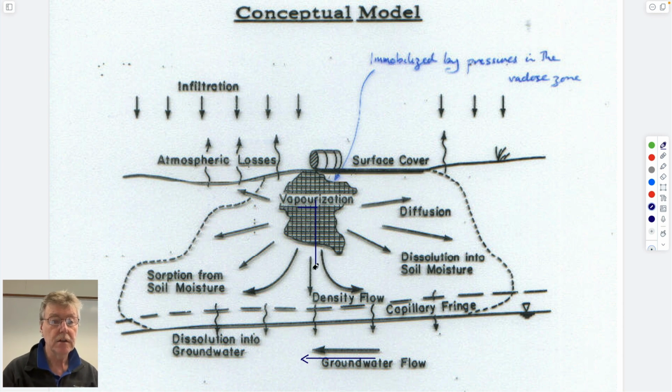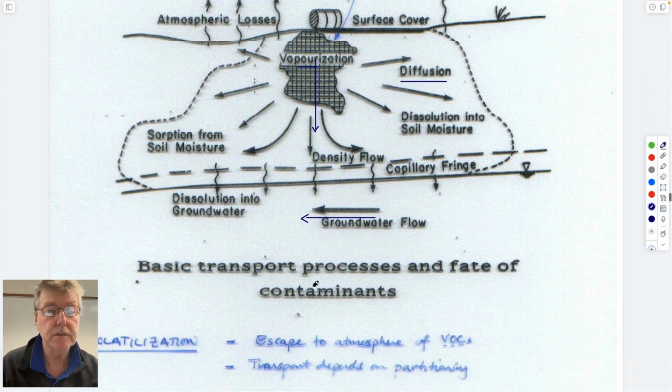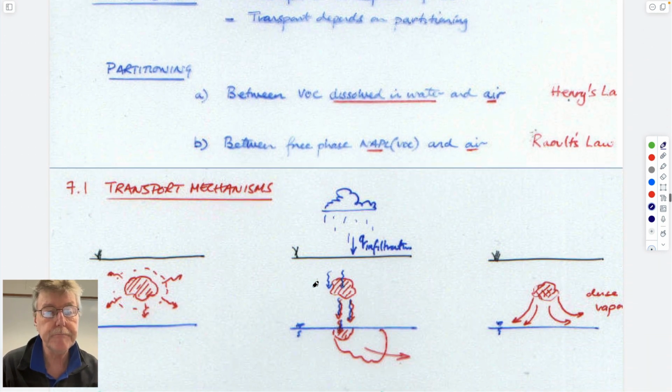So we'll really talk about two mechanisms of transport of the three. The two we'll talk about are diffusion in the vadose zone in the gas phase, and advection due to washing out by water from rainfall in the aqueous phase. We won't talk about natural convection by negative buoyancy, right? Being denser than air, it travels downwards. So those are our processes.